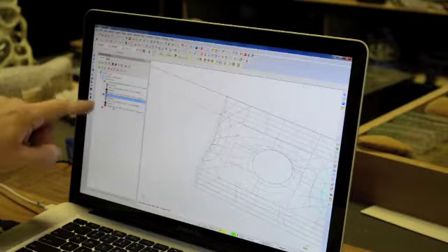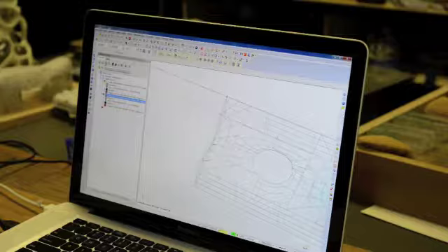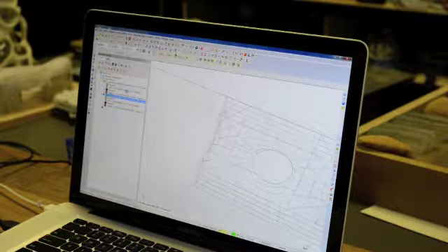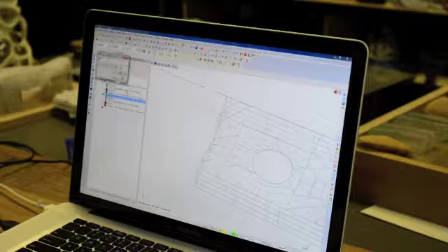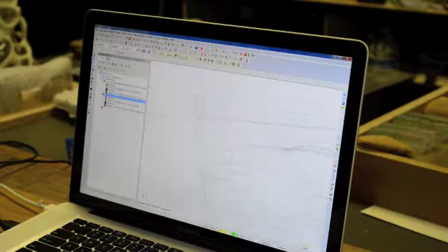And then over here, because we copied it, we have to manually regenerate the toolpath. So when you see this little X over here, you can just click on that, or up here there's these toggles too to regenerate the toolpaths. So when you do that, you get this little error message, just click the green check mark, and again click off on the back plot, and you'll see that it generated the toolpaths.